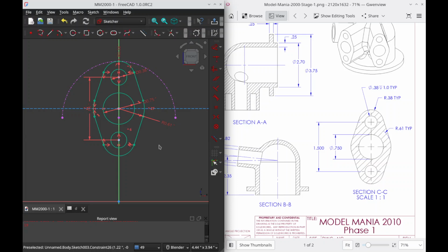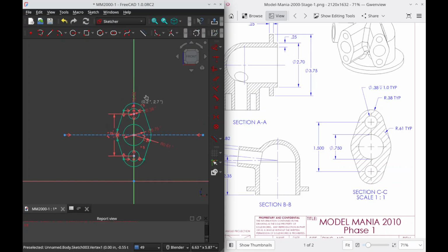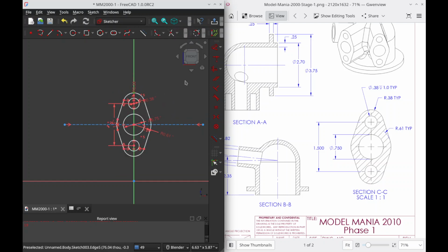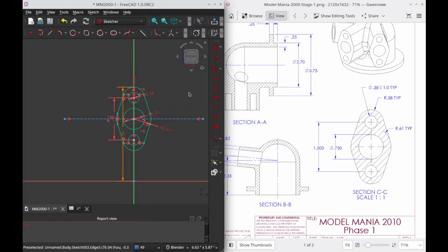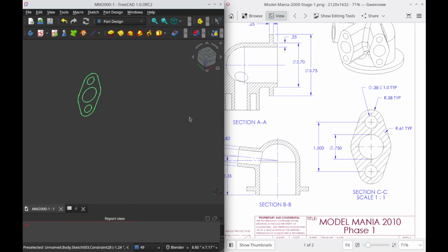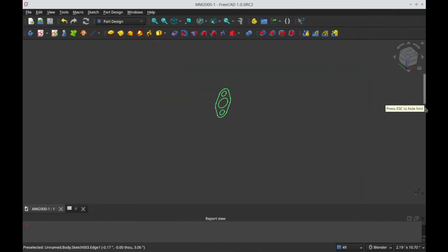We got there. So this actually is really just like a master sketch for the flange. The only thing it references is this top level height. Something I might actually do is delete this, and now this moves up and down. Press I, and set that equal to d.top level height manually. That way we're not depending on any external sketches or geometry. And that's that. So we can hide that, bring this back to full screen.